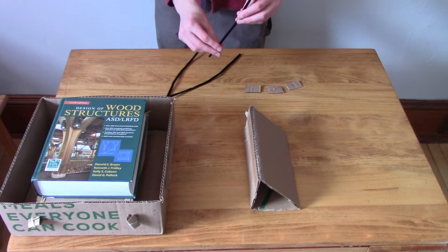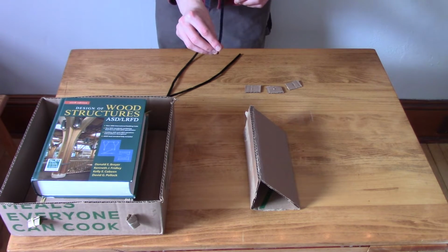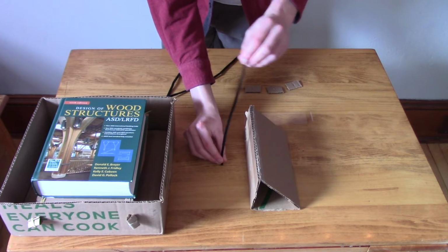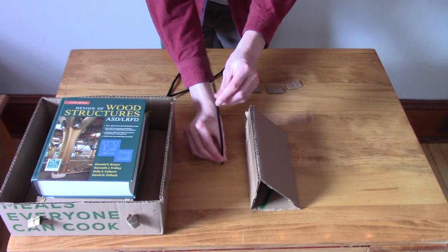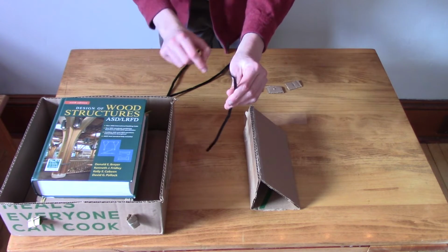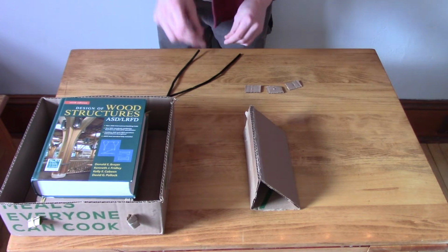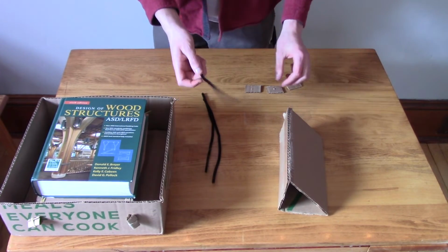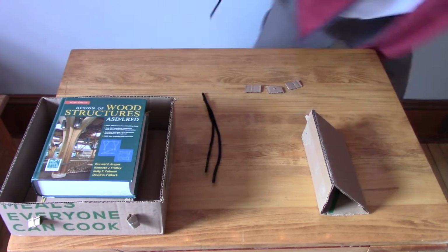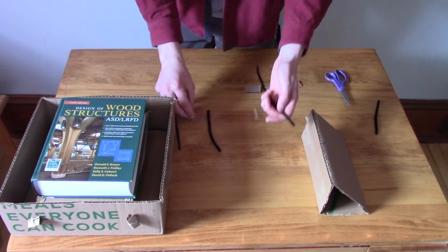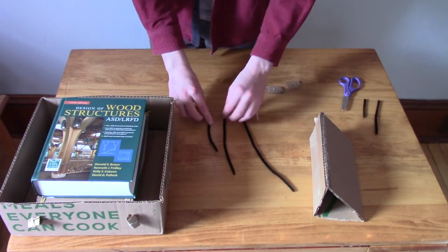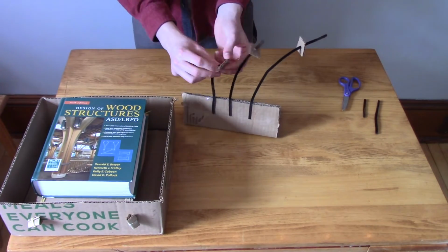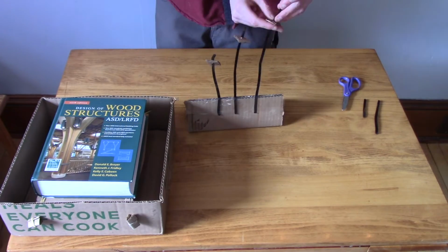to model individual structures. Now if you notice, every structure has a fundamental frequency that it vibrates at. So this is a long structure that vibrates slowly. If we hold it here, it vibrates faster. To model 3 different heights of buildings, we're going to cut these to 3 different heights and then tape them here. As you can see, we used equivalent weights modeled through the cardboard squares shown for each structure to keep all variables constant besides structure height. This is done in order to effectively model fundamental frequency.